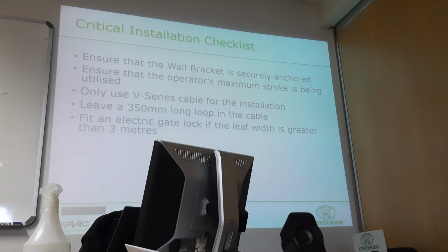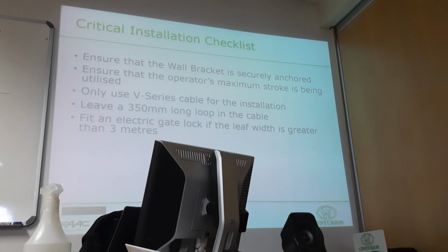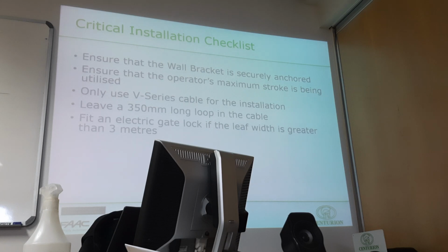But if it happens every day, yes, there's going to be some wear and tear on the motor, especially on the gearbox. So yes, try not to do that. Try not to do a manual lock. Try to have a lock that gets commanded by the controller. The controller will unlock the lock before it actually starts moving the gate.